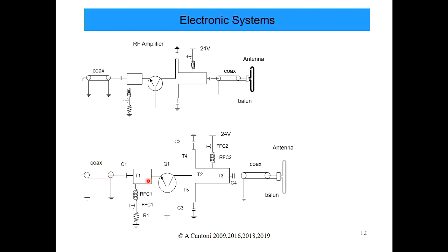And you may remember last year, did any of you do 3021 with me last year? No? Okay. In 3021, one of the things we talked about was these lossless circuits of inductors and capacitors that can effectively transform the impedance from one input port to the other port, so that they look different. We were mentioning that that's what they do for a lot of RF amplifiers, to match the output impedance of the transistor to that of perhaps the coax. And that's exactly what's happening here.